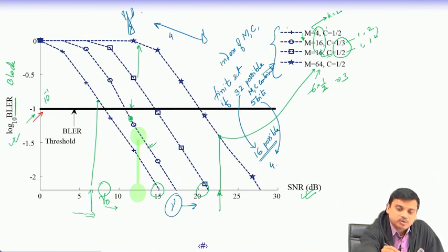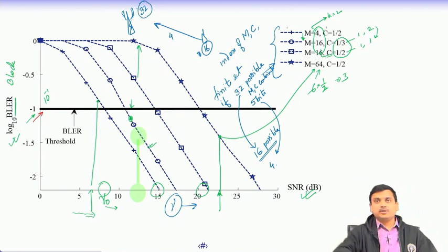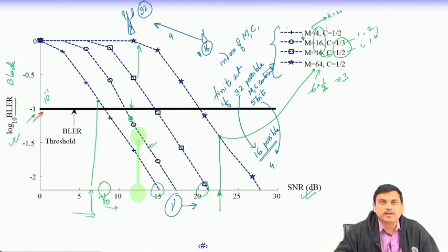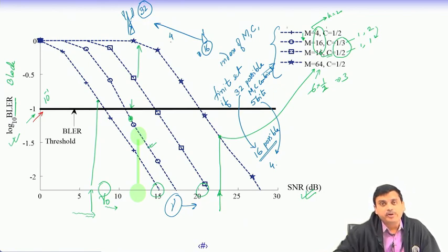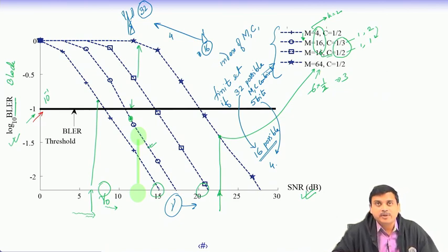So, the base station knows that from 16 levels it gives a feedback, but the base station knows that there are 32 possible levels. So, using prior information about the block error rate which the user has been sustaining, the base station has the flexibility or decision making capability to either allow the particular MCS of choice, or reduce it by 1/2 step or increase it by 1/2 step.